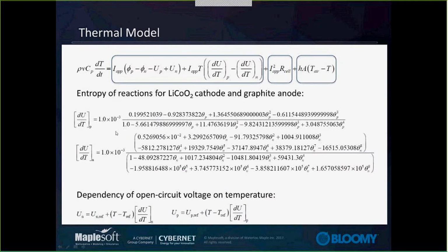The open circuit voltage is also affected by thermal properties, so we made sure to include our thermal characteristics. So whether it's the loss power that you'll use as the applied current is lost through the heat inside the cell and that's not recoverable, or the cooling system that's added to the cell itself, we have that modeled, as well as the enthalpy change effect that is going to be changing the behavior of whether the cell is heating up due to charge or discharge, and the contribution from the two half-cell circuits.